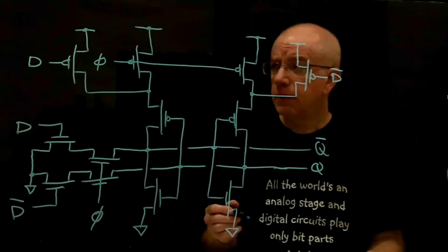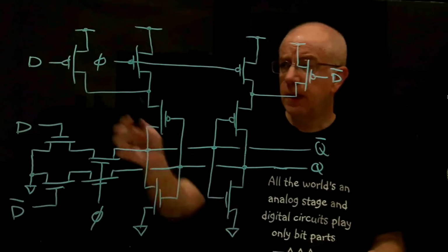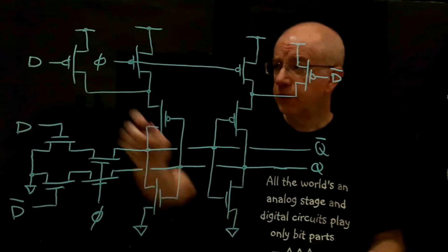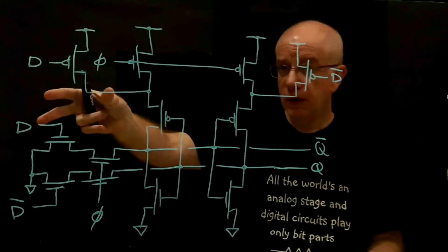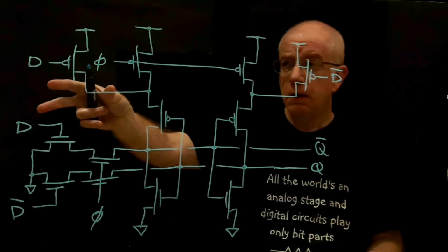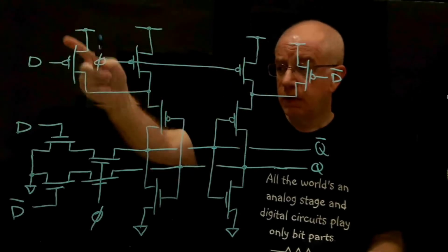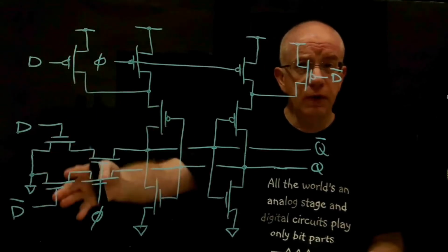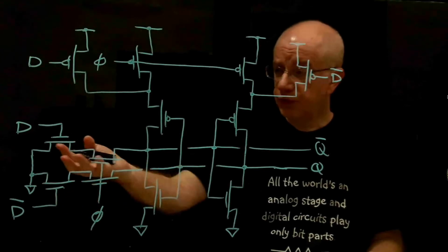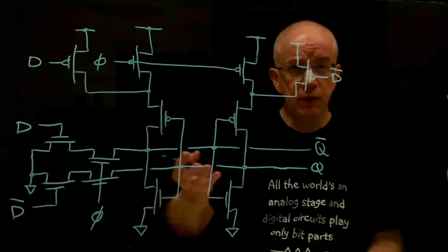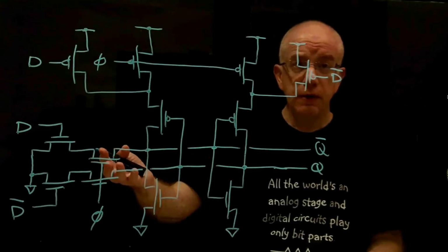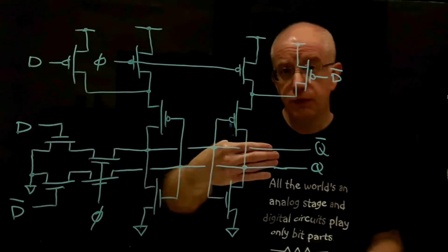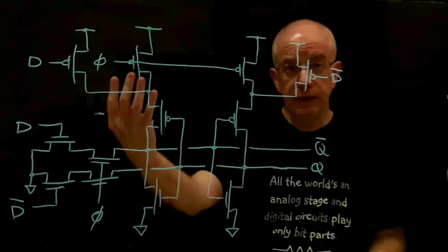And now we would like to do something about the D transistors up here, and obviously we could do a similar kind of thing. That is, bend this D transistor down this way and move this one over in a position above that first one. Okay, that way all the D inputs are localized over here on the left-hand side of the cell, and we've started to arrange these transistors as they might be in a standard cell type layout, where you have these diffusions going this way parallel to the power rails, and the poly gates going up like this.